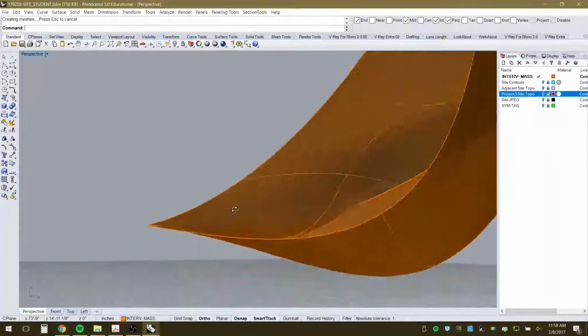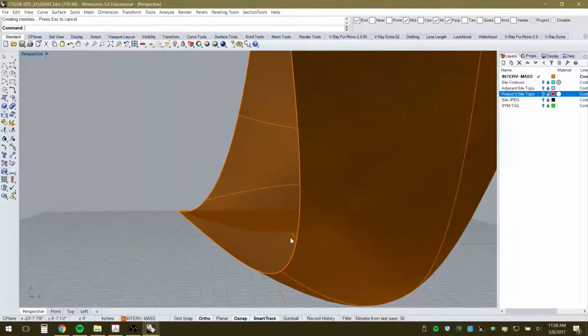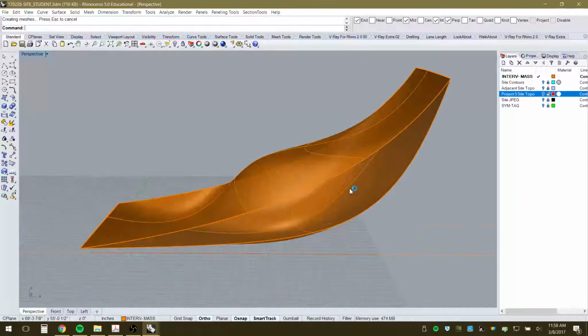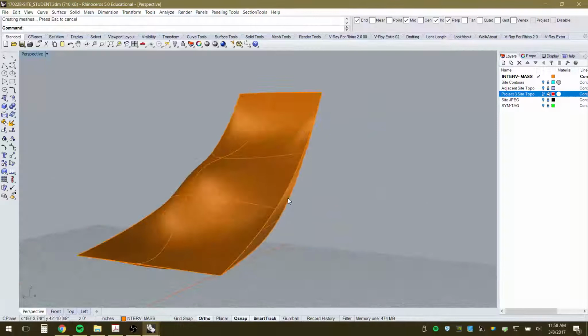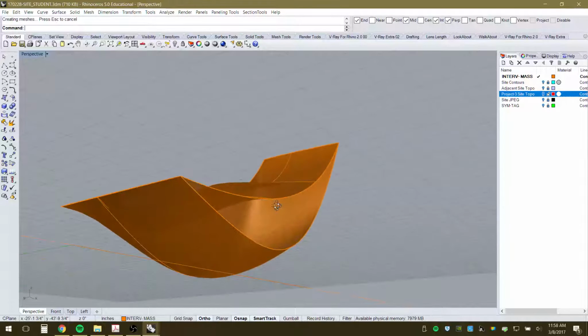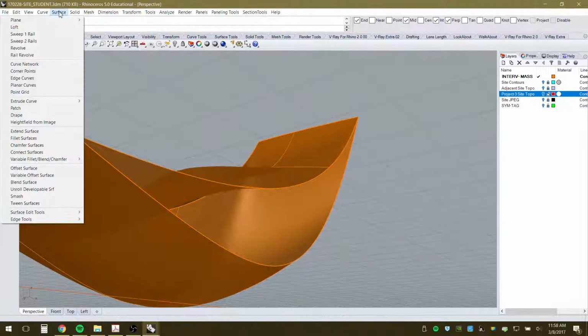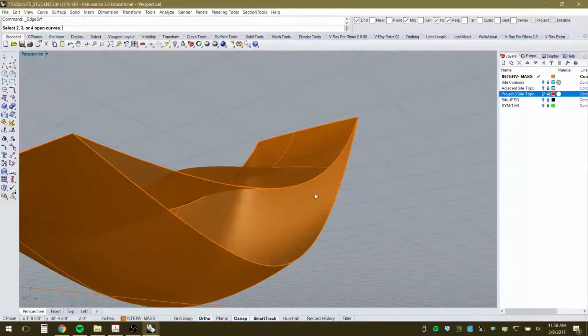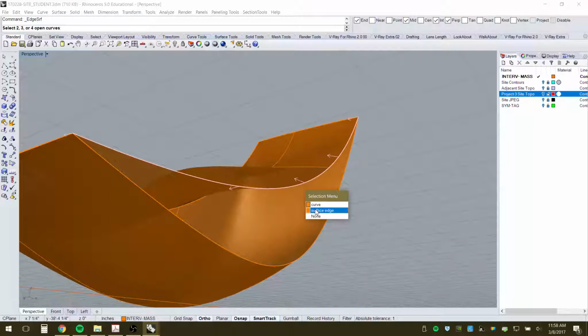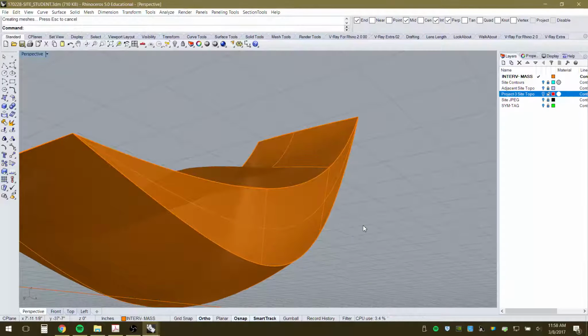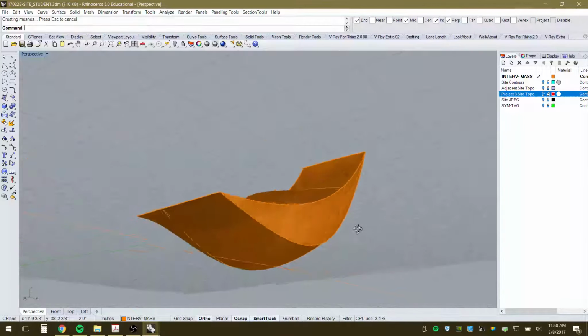And now I want to close up this edge, right, because I have this funky edge that's closed up. I have curves there, but even if I didn't, if I just had the surfaces, I can use and select the surface edges to create a surface there. Surface edge curves, so I want that edge. It's still selecting the curve, which is fine, but you can see here, this is the actual edge of the surface selected. So I can select that, do the same down below, enter, right click, I'm just right clicking to enter, and now I've created that surface.